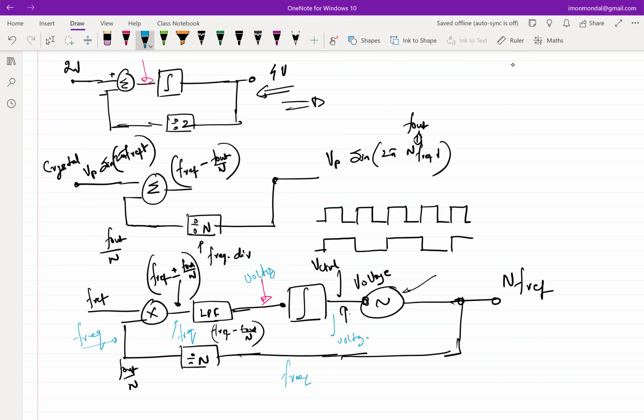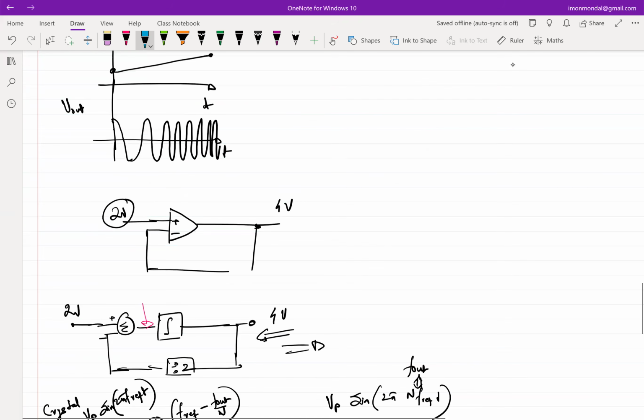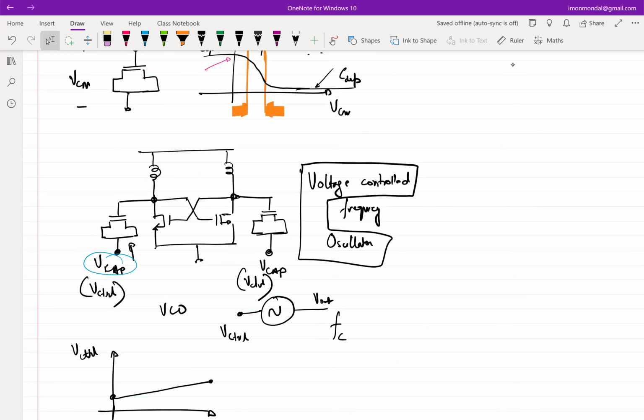At the output of the integrator, the integrator input is DC, right? Because the low pass filter has almost 0 bandwidth. And the output of the integrator is also DC, right? You are integrating, you are ramping. The only way the ramp can stop is when the loop settles to the value that the VCO wants to get, N·f_ref. Yes, right? Because ultimately, what is V control? V control is this guy. So you connect the VCO inside the loop.